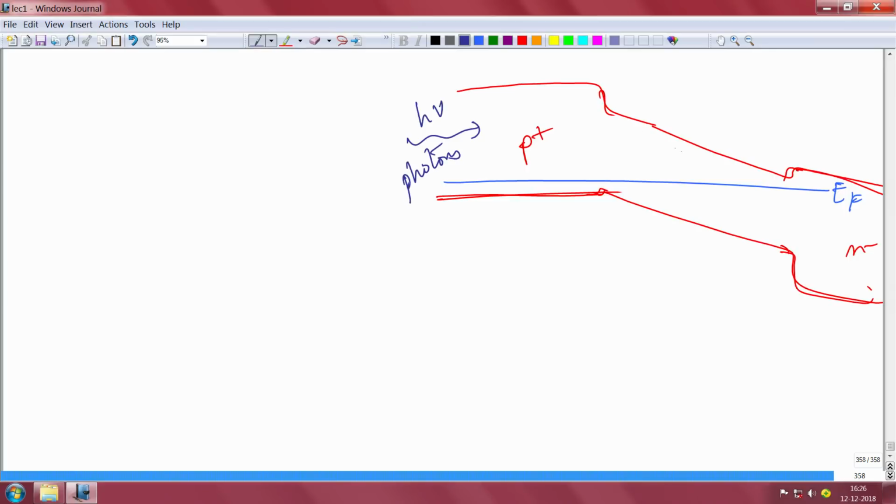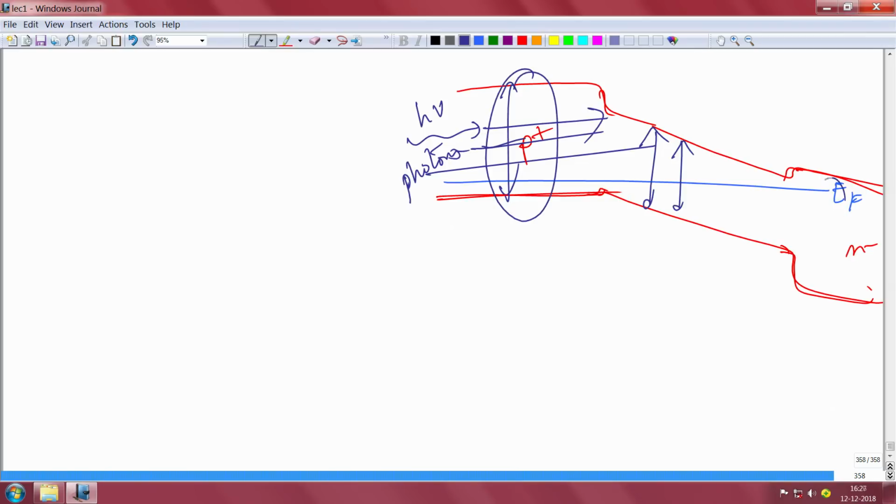These photons that correspond to the bandgap here will not get absorbed here, because this is a wider bandgap. So all the photons that are shining that correspond to the bandgap in the intrinsic layer will definitely pass through very easily. It will not get absorbed in the P type layer or N type layer, which will not lead to any useless waste of the carriers. So slightly heterojunction photodetectors are also used. There are advantages and disadvantages also, of course, in any case.